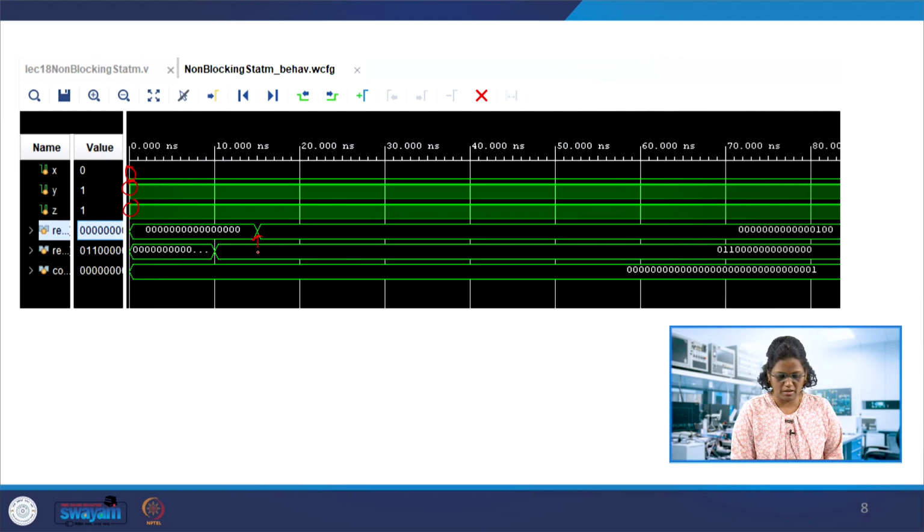That's the case with the previous blocking or non-blocking, same as that, but the value is evaluated and it is assigned only at 15. After 15 time units, this non-blocking assignment has taken place. And then because of the delay hash 10, the next statement reg B is at hash 10. It's not hash 15; after that hash 10, that is at 25. This hash 10 can see changes in the last 3 bits, and that's because of the non-blocking statement.